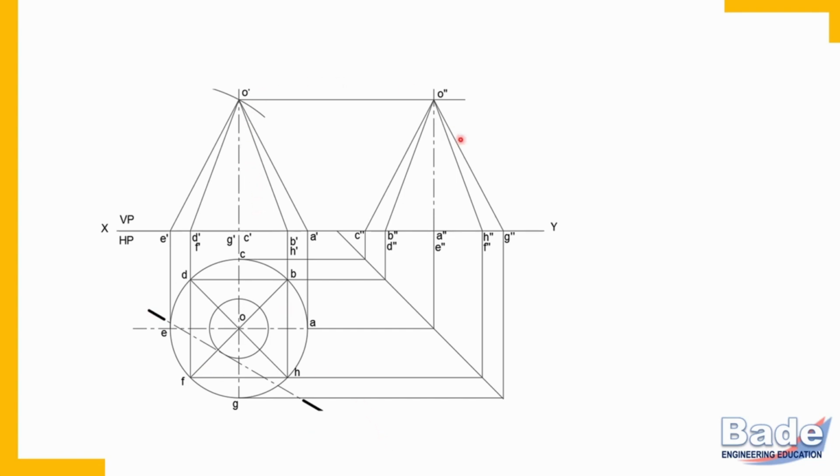So two important steps in problems on sections of solids: position of the object and position of the cutting plane. These two steps are over. So now there is really no possibility of mistakes. But try to understand here something new now. As usual, first we'll label the line of points of intersection of the cutting plane line and generators of the cone. P on generator OE, P on generator OF, P on generator OG, and this cutting plane cuts the base.